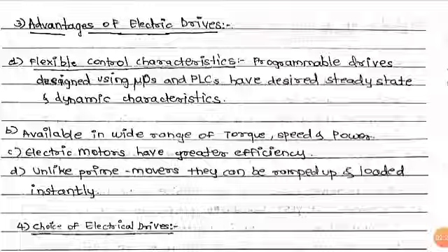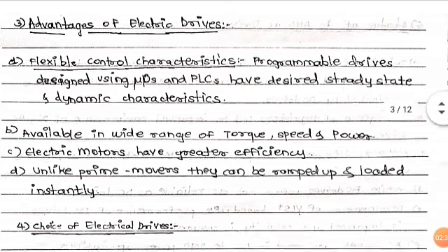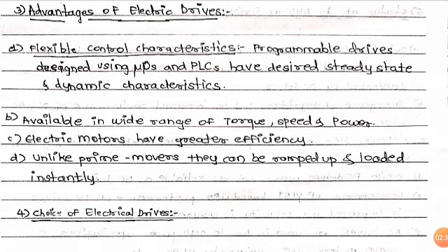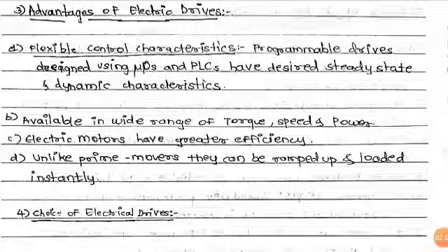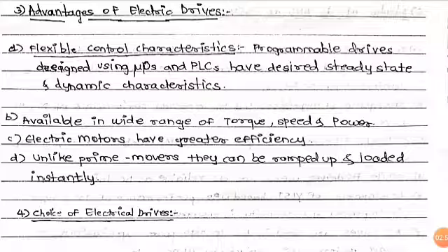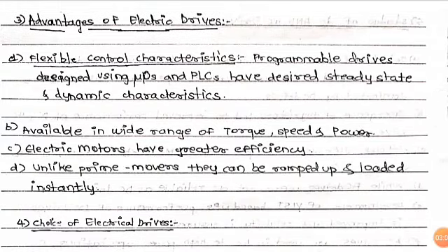Generally we know that we plot torque speed characteristics of machines. So on the characteristic we can choose the point of 1000 rpm, on mostly the y-axis in drives, and on x-axis there is torque. So we can select the desired torque from x-axis and desired speed from y-axis. Just see where these two points intersect the motor characteristic, and that is the operating point.